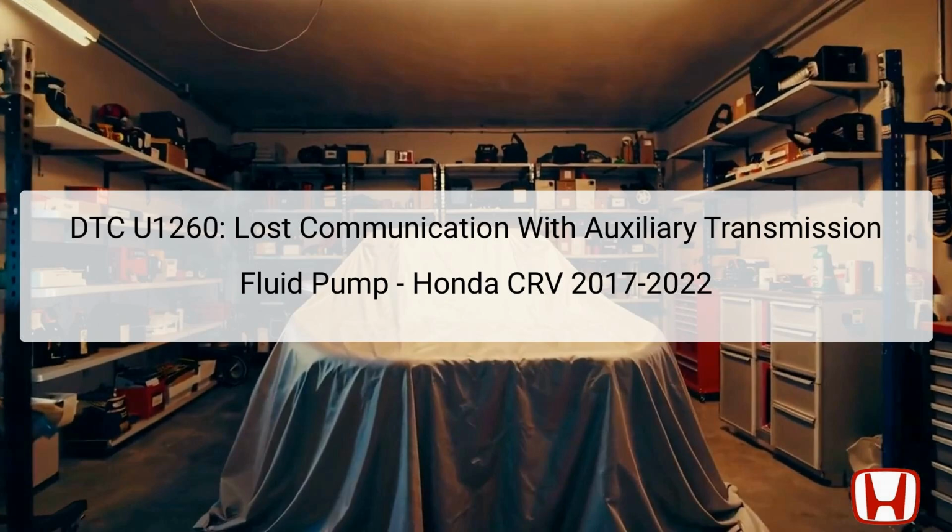The U1260 Diagnostic Trouble Code, DTC, specifically indicates a lost communication with the auxiliary transmission fluid pump in a 2017 to 2022 Honda CR-V. This code is primarily linked to communication issues between the vehicle's transmission control module, TCM, and the auxiliary transmission fluid pump. The auxiliary transmission fluid pump plays a critical role in the CVT, continuously variable transmission system, enabling proper fluid circulation and pressure, essential for optimal transmission performance.